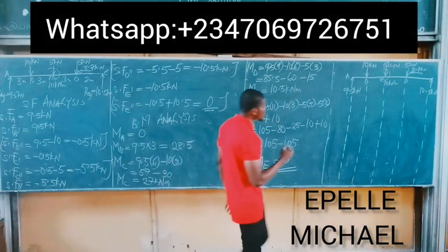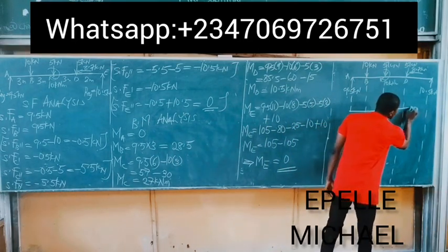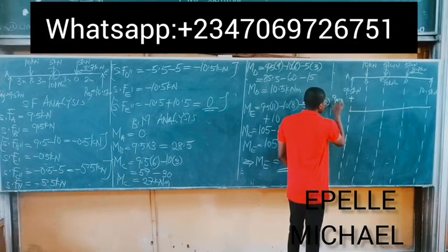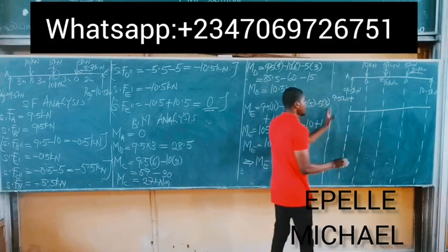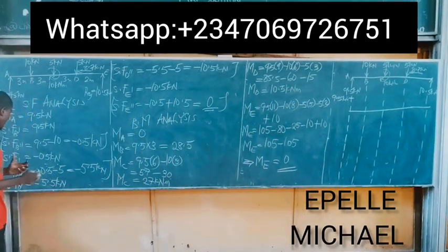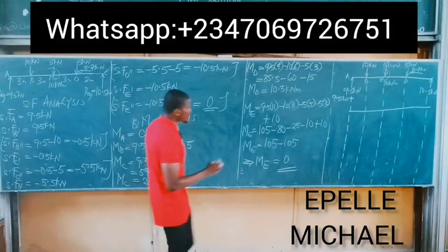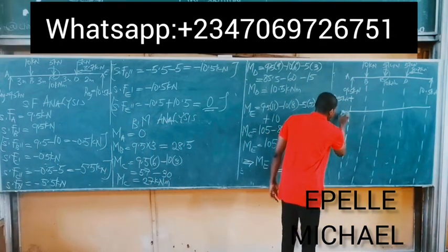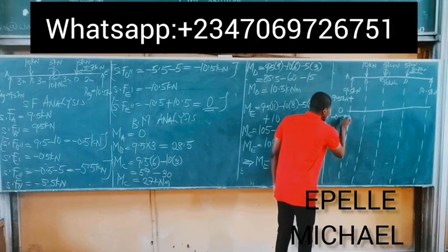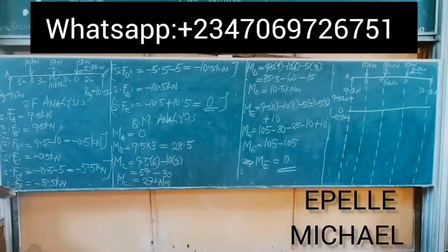So we draw our origin line. Above the origin, the values are positive. So the only positive value we have is simply 9.5 kilonewtons, and you indicate that. From the negative values, the lowest is simply minus 0.5, so you put it down near the origin line. So here is minus 0.5 kilonewtons, that's shear force at B prime prime.